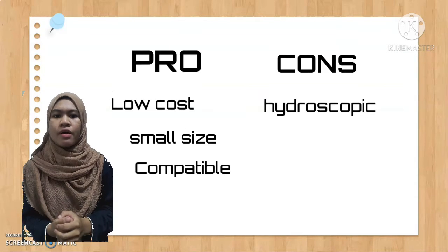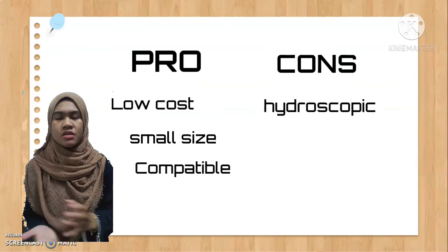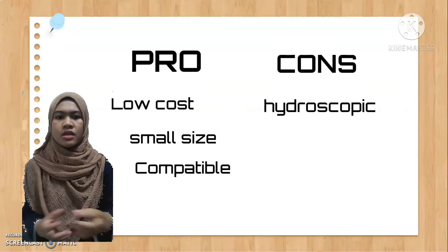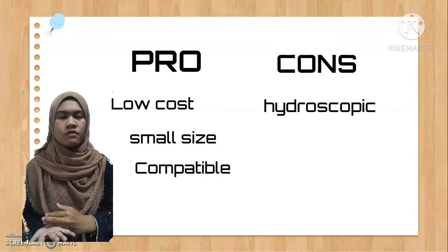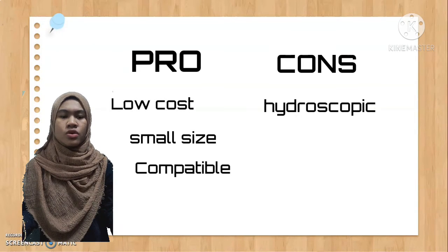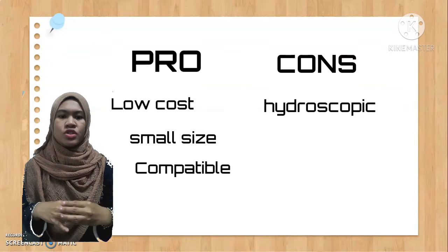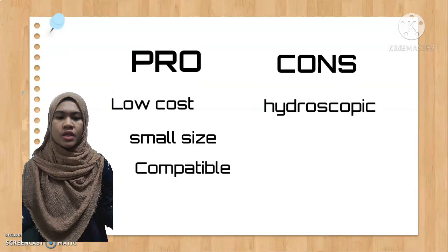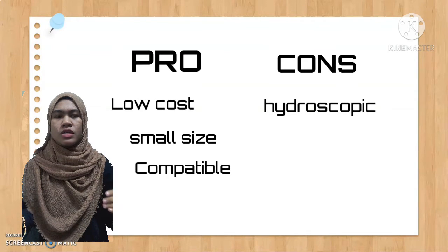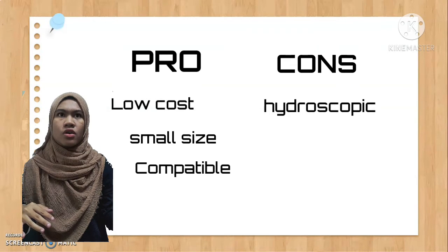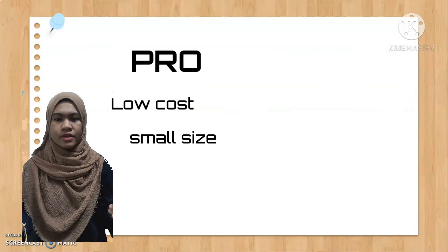Actually, there are issues with plastic packaging. Plastic packaging is hygroscopic and absorbs moisture to a level dependent on the storage environment. This moisture can vaporize during rapid heating, such as in a solder reflow process, and these stresses can cause the package to crack.